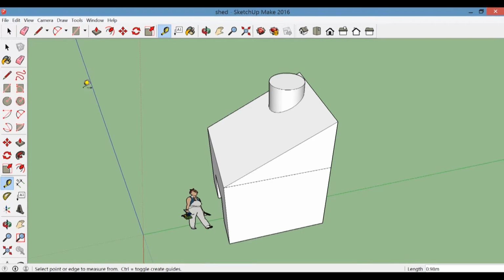So the software highlighting the circle is an example, but if you have a line or a rectangular prism on this shed, and you point a tool, let's say another line, on the vertex or one of the other vertices, it'll highlight to you where exactly that corner is. So I can, for example, continue this line and draw another wall on the side. There are also snaps to the middle of lines, to different axes, and so on. And snaps are meant to be intuitive, and you'll often find that whenever you're thinking, hey, I wish that something will appear that will help me find where this corner or that center or this point on the line is, chances are what you're looking for will end up appearing.